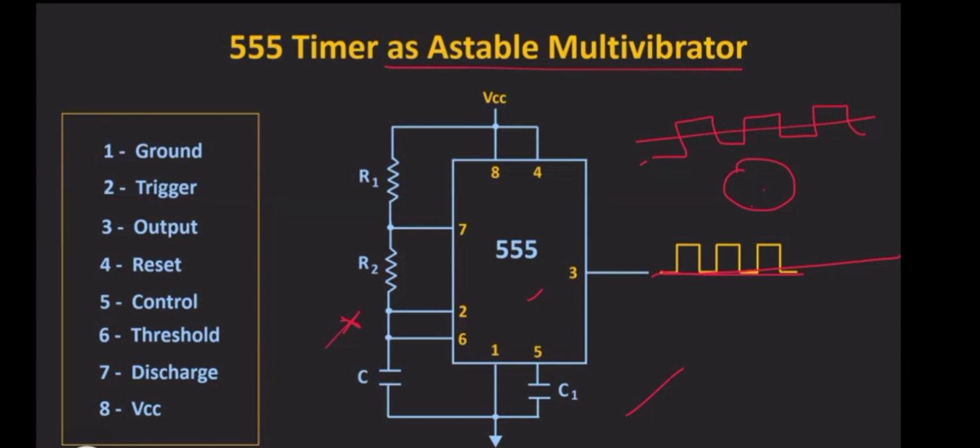And astable multivibrator means there are two states, which are known as the on and off state. Both states are quasi-stable, so both states will not be stable. You have to design with an external circuit, R1, R2 as well as C. Since we are using T1 and T2, we have used two external resistors and one capacitor. It is clear.